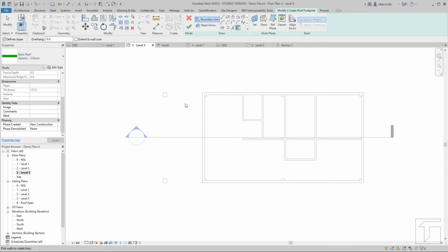So this is already good. If you draw here in Revit regarding roofs, it will take you to a sketch mode. When you say sketch mode, it's as if you're going to do a drafting. On the draw panel, under modify, creating roof footprint, you will have different shapes that you can draw. For the roof, I'll just use this rectangle command. Let me click to choose that.